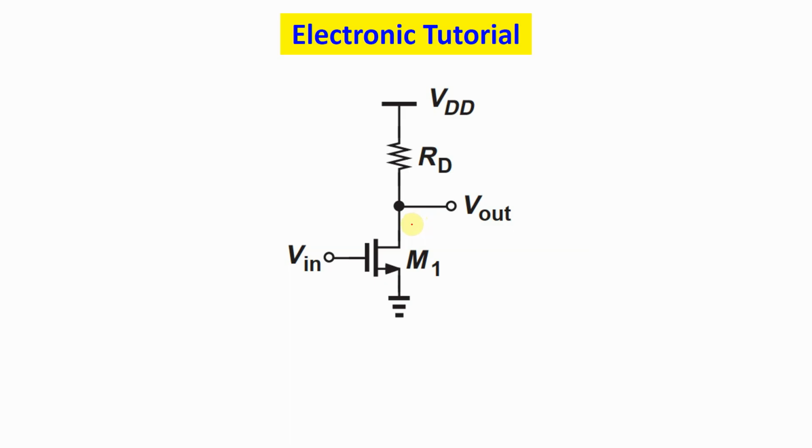and after that I'm going to give you a good example of how you can calculate the gain by just inspection, and this is important, and how we can apply it to other common source amplifiers as well, just by seeing the resistance at different nodes of this amplifier. And then I'm going to calculate the condition for this transistor to work in saturation, because this is the assumption that we have to make in order for this transistor to work as an amplifier.